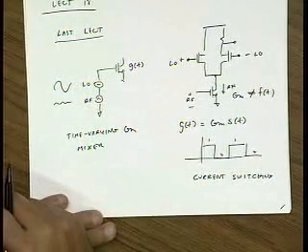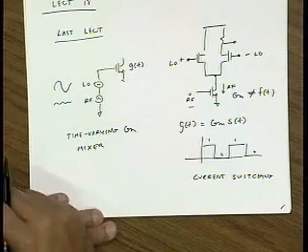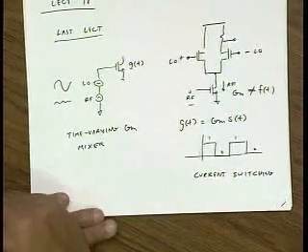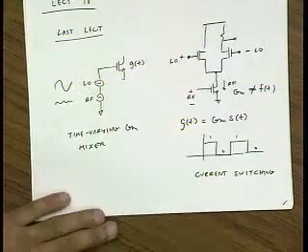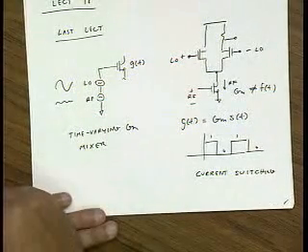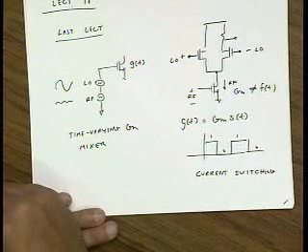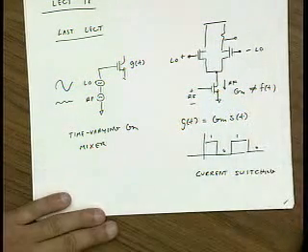Okay. And so now you can dream up other ways of building a mixer. For instance, if I have a voltage-controlled resistor, and I vary its resistance periodically and run RF current through it, you get a mixer. So any periodic time-varying circuit will act like a mixer. Okay. Is there a question?